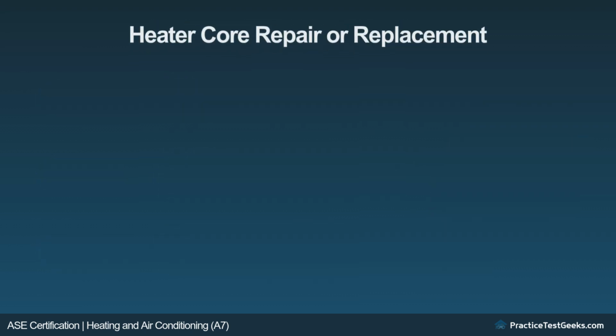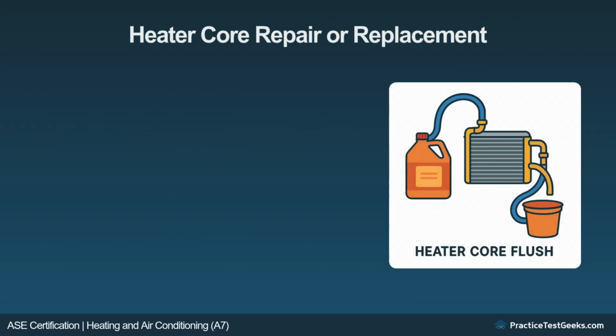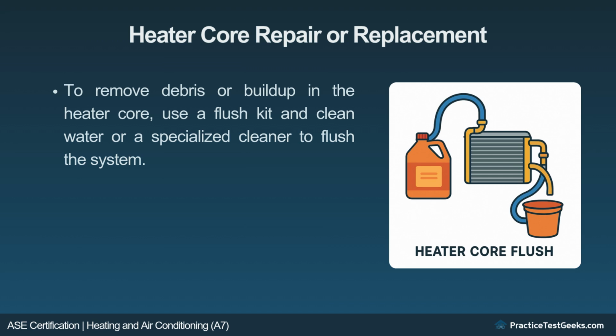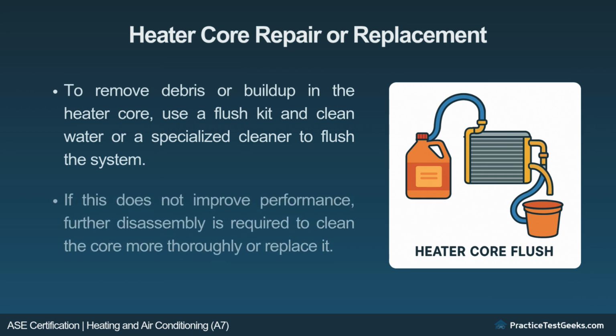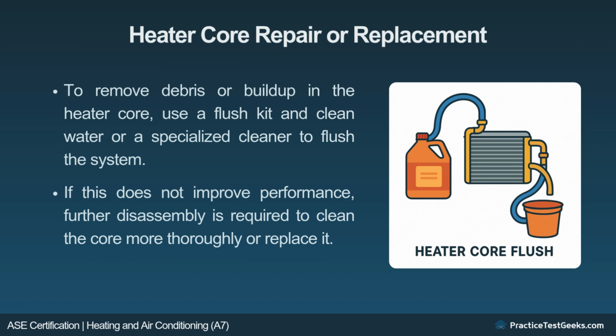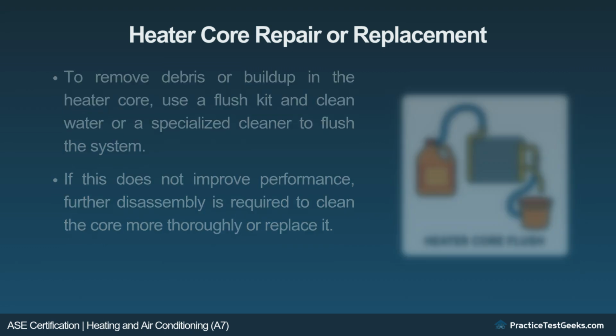Heater core repair or replacement. Heater core flush. To remove debris or buildup in the heater core, use a flush kit and clean water or a specialized cleaner to flush the system. If this does not improve performance, further disassembly is required to clean the core more thoroughly or replace it.